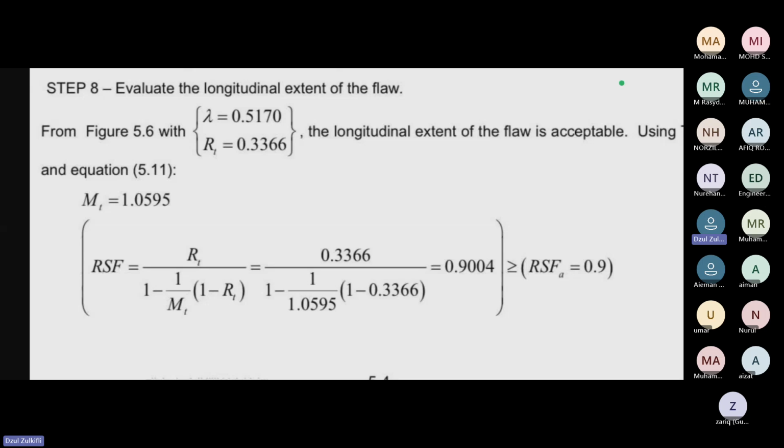Okay. MAOP ni I think lah, to be honest pernah dengar tapi tak berapa ingat the definition, tapi just by virtue of the term is operating pressure kan, it is naturally lower lah daripada working pressure. And I think when we talk about operating pressure, probably there is a function of input from process people perhaps, and also the operator and also the owner of the equipment lah, on what is the safe operating pressure, more from a process standpoint kalau tak silap. Not really from mechanical standpoint. Mechanical mainly MAWP lah yang penting.